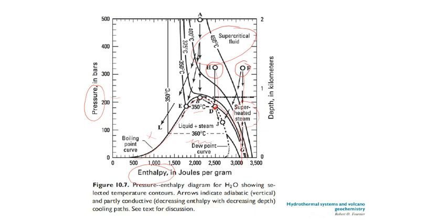If the decompression is accompanied by a loss of heat, the fluid will also join the two-phase zone here, or even directly the pure liquid zone here, depending on its initial enthalpy.